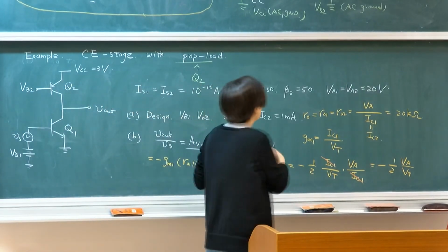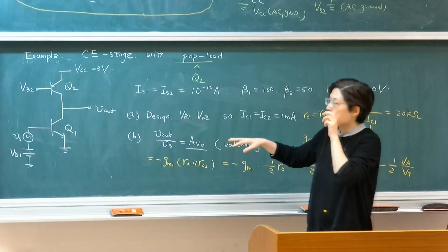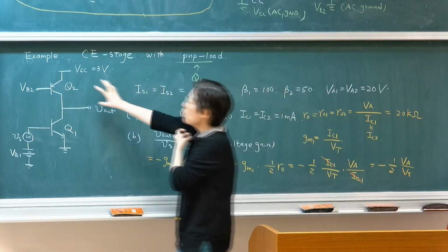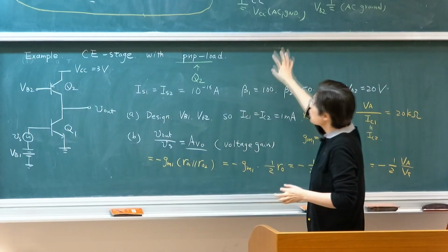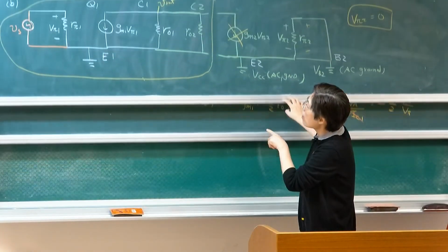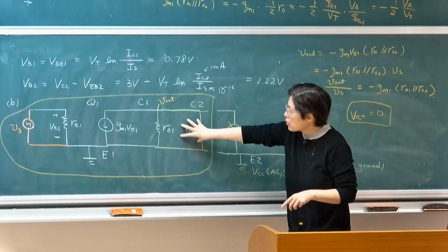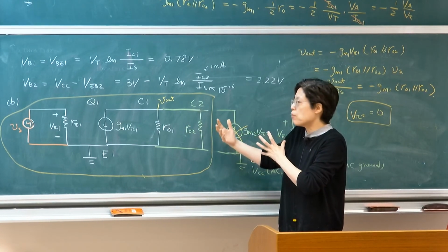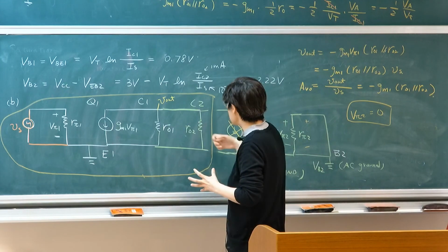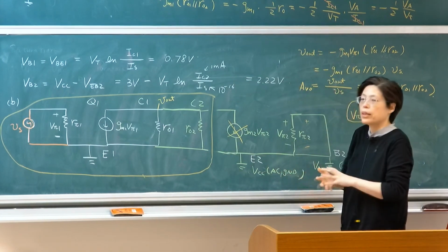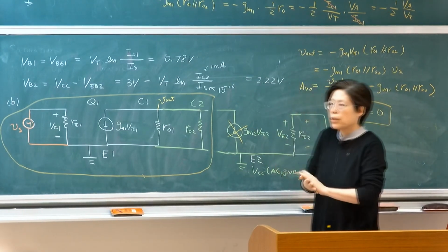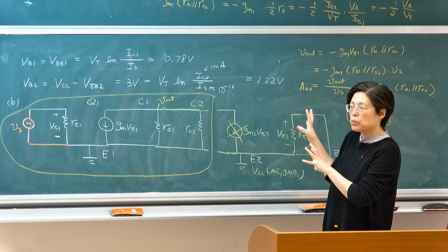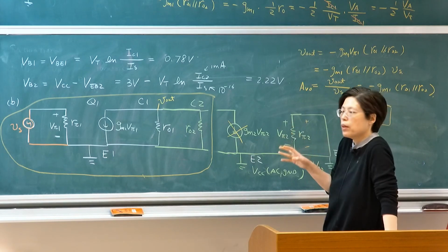We're going to talk about that a little bit more. But that's just to tell you that when you use a PNP with an active load, it introduces a resistor that contributes a resisting or loading component, which leads to the limitation of your overall gain of the circuit. Okay? So I'm just going to stop right here regarding the discussion of chapter 4.